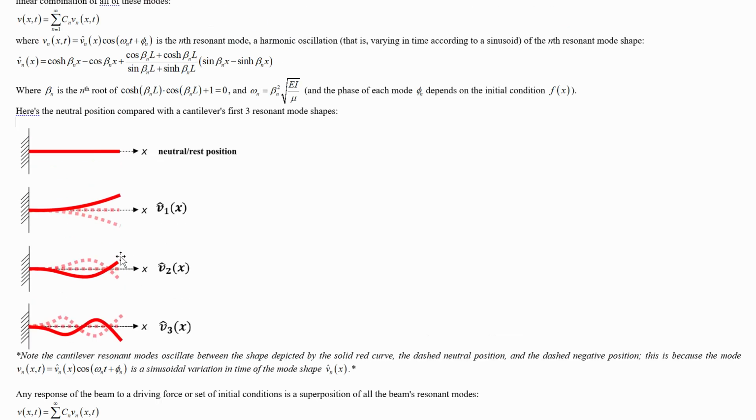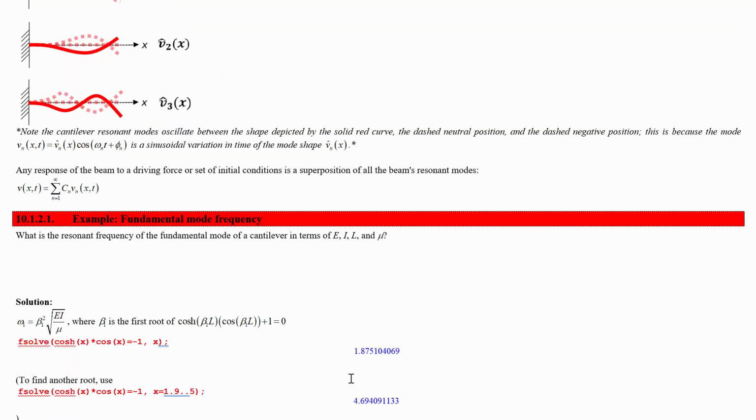This is a bit of a sketch, and we'll look at the real solutions later, but this gives you the idea. The extra cantilever modes end up having displacements that cross back and forth, and because they don't go all in one direction like the fundamental mode, this one ends up having a lot more displacement from equilibrium for a given amount of elastic energy required, so is much more dominant in terms of the overall response that you witness. So let's explore this.